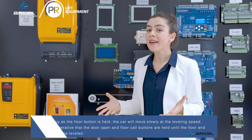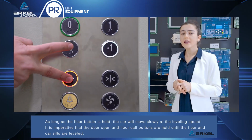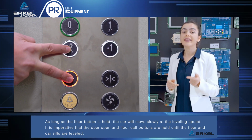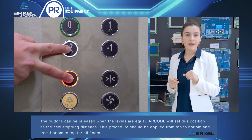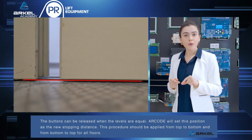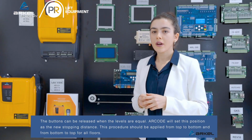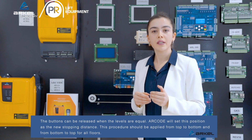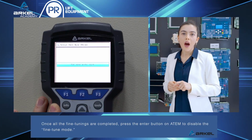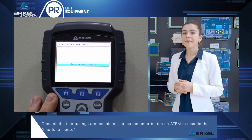As long as the floor button is held, the car will move slowly at the leveling speed. It is imperative that the door open and floor call buttons are held until the floor and car sills are leveled. The buttons can be released when the levels are equal. Arcode will set this position as the new stopping distance. This procedure should be applied from top to bottom and from bottom to top for all floors. Once all the fine-tunings are completed, press the Enter button on RM to disable the fine-tune mode.